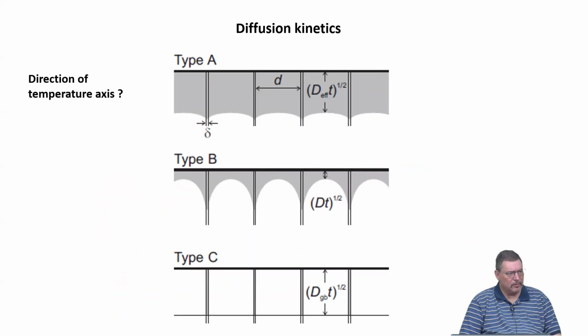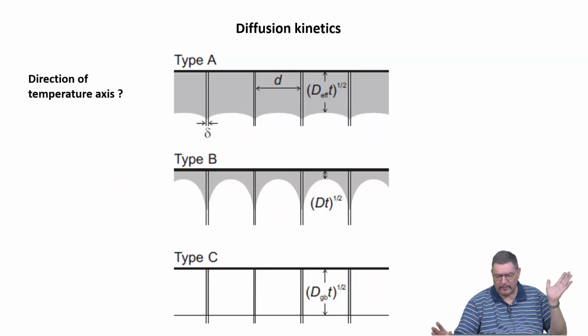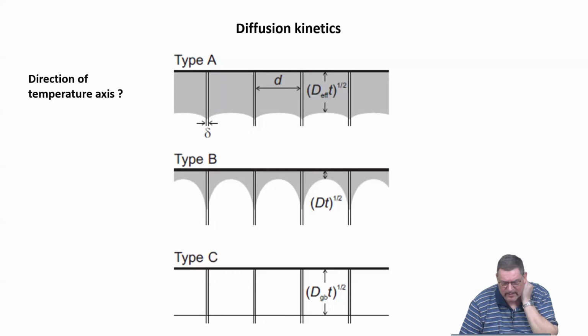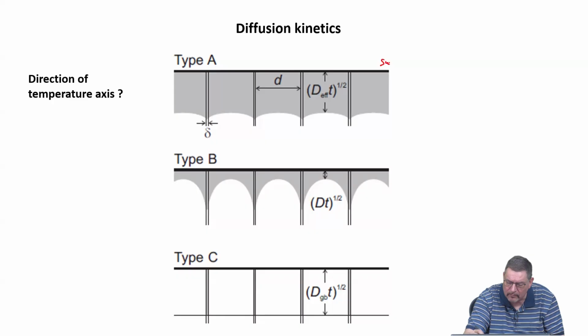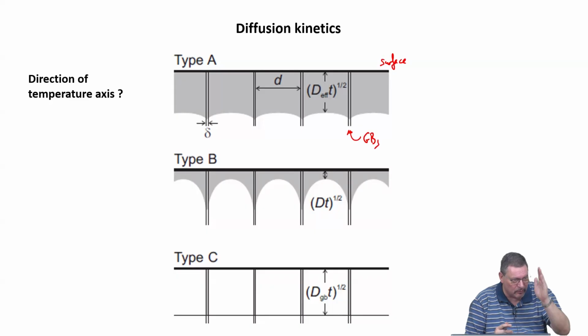So we are now going to grain boundary diffusion, right? We have cut out the surface, no dislocations. This is then a simplified view. We have an open surface, which has been nicely polished to mirror finish. And we have some grain boundaries in the material. For the sake of simplicity, they are all arranged in a way that they would perpendicularly cut the surface. They have an average distance d and a thickness delta.